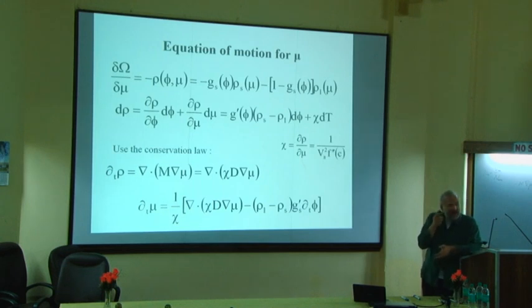So remember, yesterday I made the approximation that the diffusion coefficient is a constant, right? This makes the mathematics particularly simple. For alloy solidification, this is a very bad approximation, because normally chemical diffusion is much, much slower in the solid than in the liquid. And so in alloy solidification, mostly people make the opposite approximation. That is, they say there is no diffusion in the solid. So instead of the symmetric model, they take this model where the diffusion is 0 in the solid, and this is called the one-sided model, because diffusion takes place only on one side of the interface, on the liquid side.